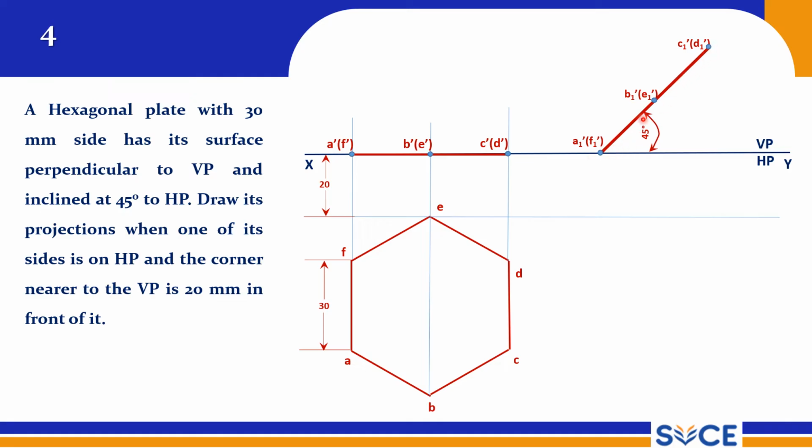Now with respect to this surface inclination, you have to draw the final top view, right? So that is the projection. And obviously since this is 45 degrees incline, we are going to get the shape that is nothing but the apparent shape only. So we are going to get a smaller hexagon than this. A horizontally compressed hexagon we obtain here.